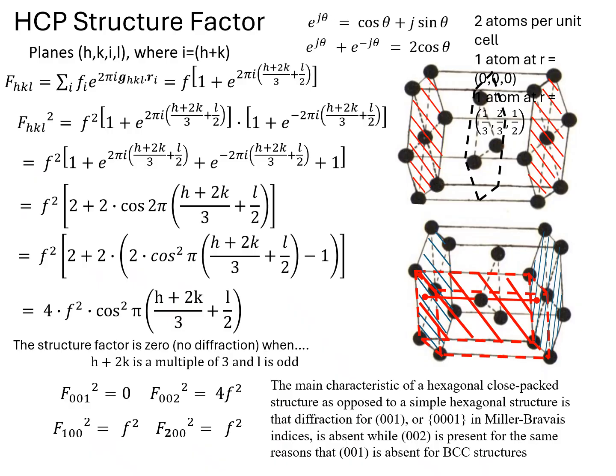It gets more complicated with the hexagonal close packed, especially when we're using the Euler form to define the phase factors, the G dot R bit. But suffice to say that when it comes to hexagonals, if you read Cullity, you'll see that the best way to show what the F factor is, is to work with the intensity.